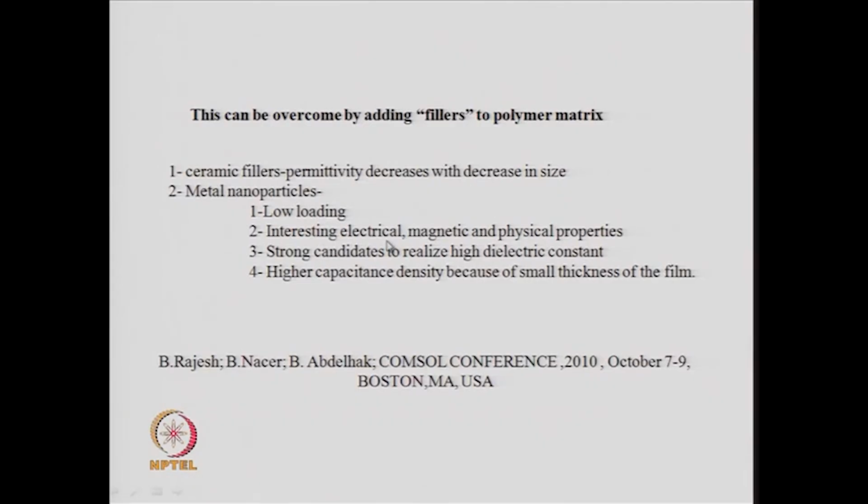They can have interesting electrical, magnetic, physical properties, and they are strong candidates to realize high dielectric constant. They will also have higher capacitance density because of small thickness of the film. So, both these are applicable. You can use ceramic fillers, you can use metal nanoparticles in a polymer matrix.